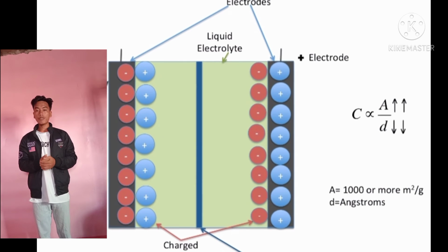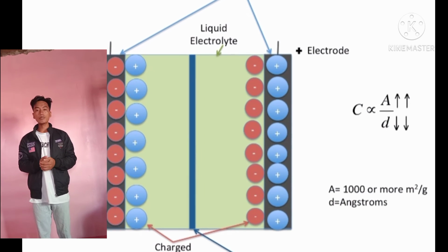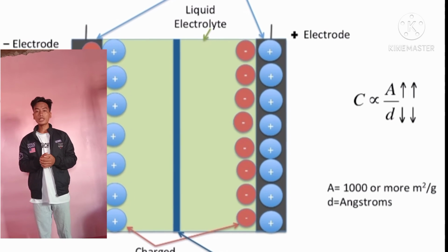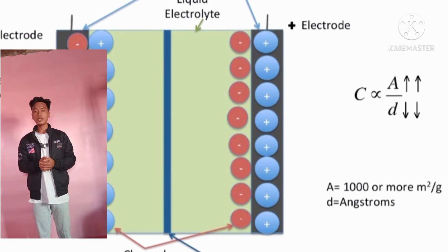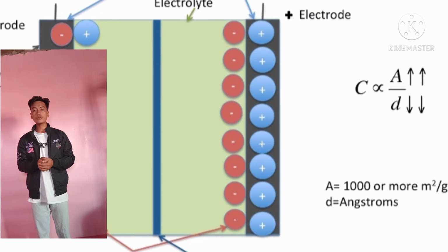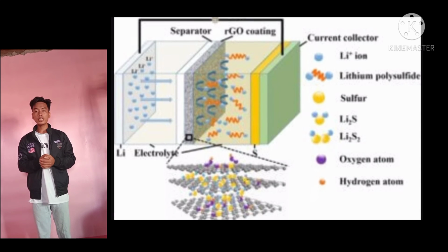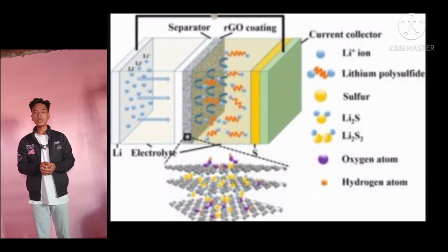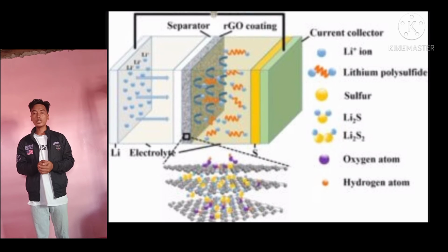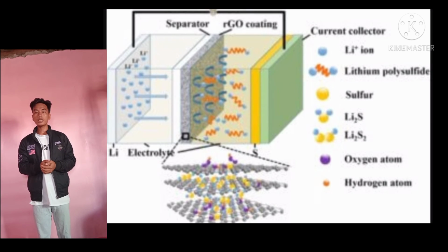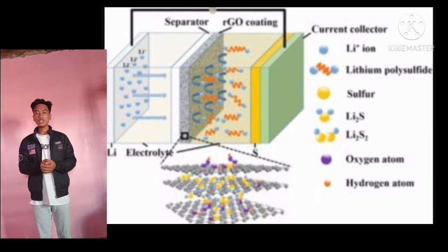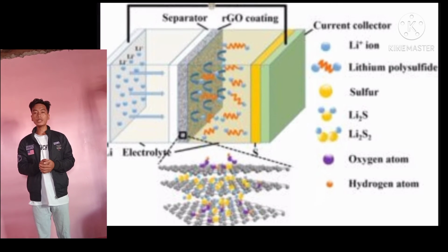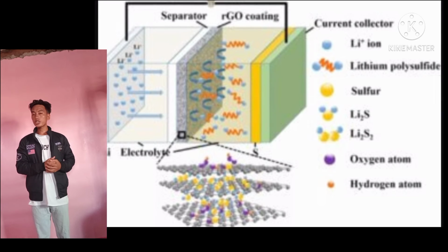Different materials such as various carbon materials, mixed metal oxides, and conducting polymers have been used as supercapacitor electrode materials. Carbon technology in its various forms, such as carbon cloth, activated carbons, and carbon nanotubes, are the most widely used electrodes. In recent years, graphene, due to its superb characteristics of chemical stability, high electrical conductivity, and large surface area, has also been considered as a promising supercapacitor electrode material.